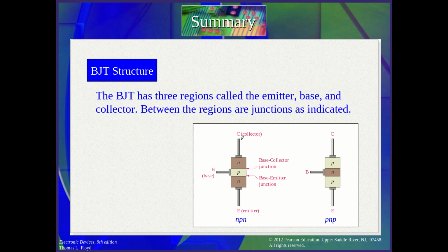In the saturation condition, there is the maximum collector current that we can reach corresponding to the IB. There is no other after that, so it is determined by the external circuit. This is the circuit that determines the value of IB according to the VCC and the IC here. So in saturation, an increase of the base current has no effect in the collector circuit.